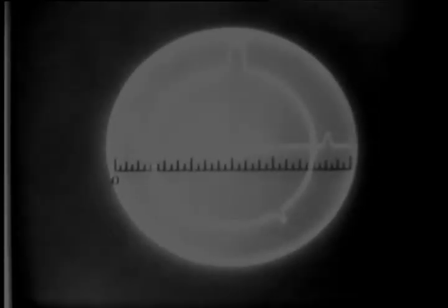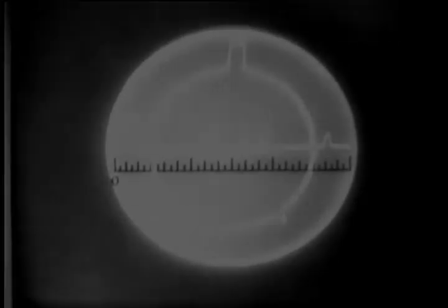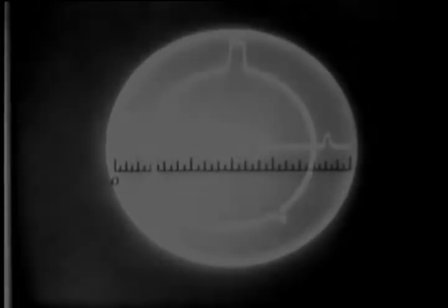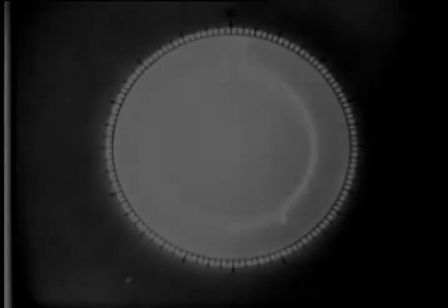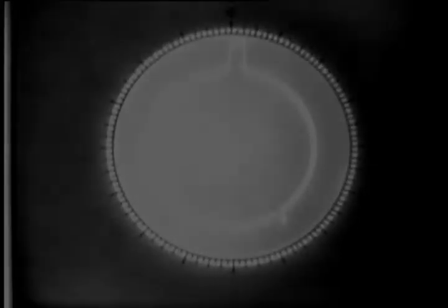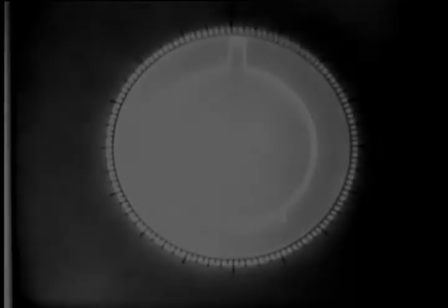But because our new baseline is circular, we can make it almost 3 times as long without increasing the size of the tube, thereby giving us a more precise means of measuring range. Since our baseline is circular, to measure range, we simply put a circular range scale around the edge, with 0 at top center. By reading range clockwise to the pip, you can tell at a glance how far away the target is. Here's that same J-scope you saw earlier.